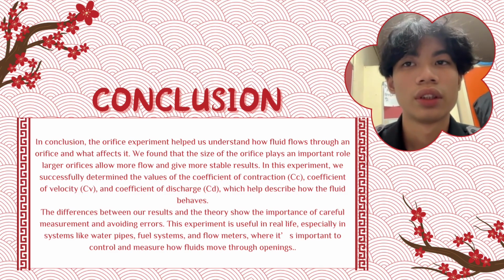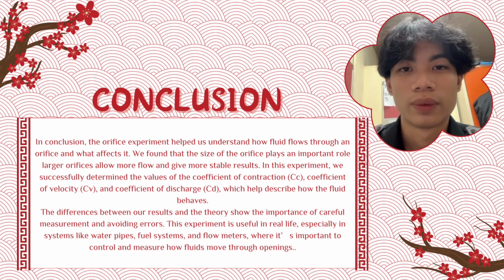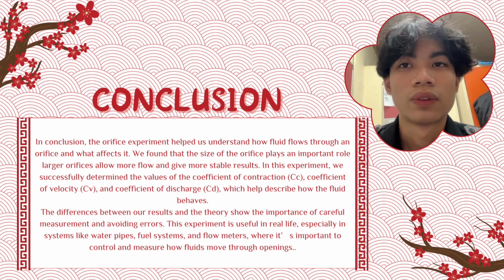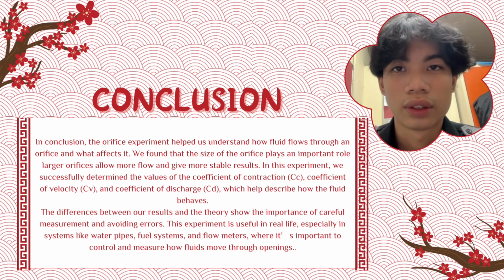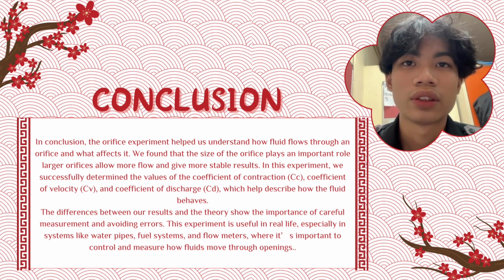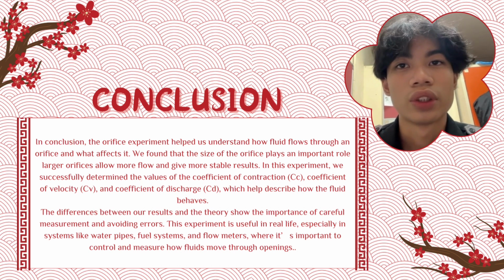In conclusion, the orifice experiment helped us to understand how fluid flows through an orifice and what affects it. We found out the size of the orifice plays an important role. A larger orifice allows more flow and gives more stable results. In this experiment, we successfully determined the values of the coefficient of contraction CC, coefficient of velocity CV, and coefficient of discharge CD, which help describe how the fluid behaves.